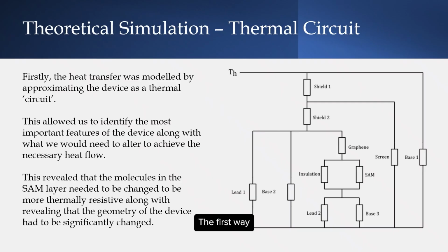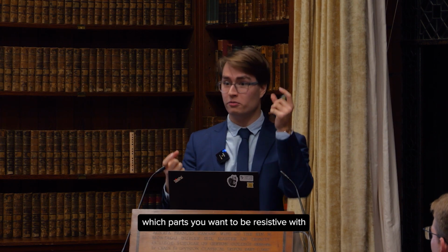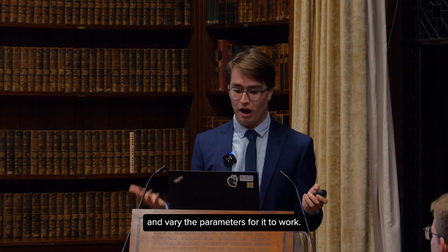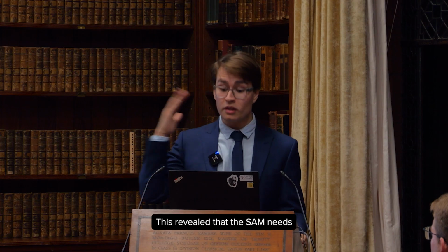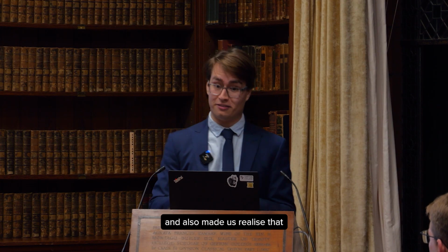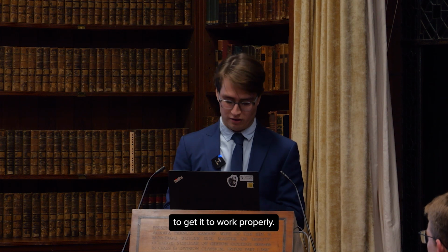The first way I was simulating this was through modeling the entire device as a thermal circuit, which is effectively you imagine the whole device as being a flow of different resistors, which instead of flowing current, you flow heat. In doing so, you're able to examine which parts you want to be resistive, which parts you want to be conductive, and vary the parameters for it to work. This revealed that the SAM needed to be much more resistive than we originally thought, and also made us realize that the geometry of the device had to be adjusted a lot to get it to work properly.